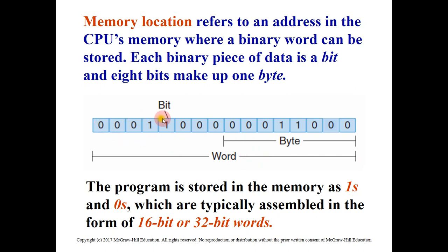Each of these bits can indicate the address or the status of one input discrete device. When we talk about a discrete device, we need only 1 bit to represent it. So if the input is a discrete device, we need 1 bit. But if the input or the output is an analog device, then we are going to talk about a word in that case.